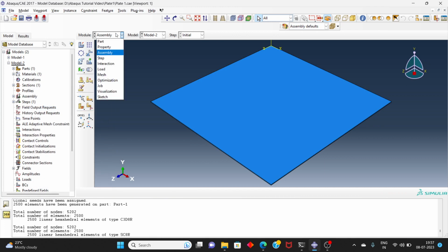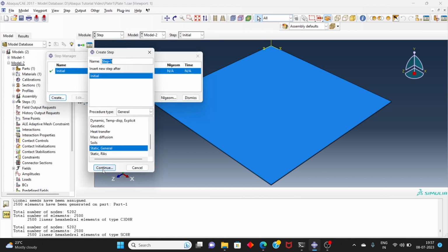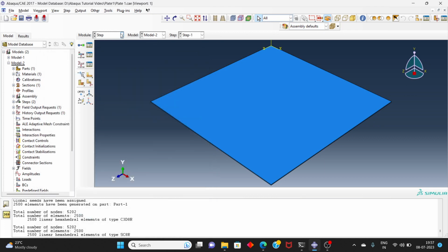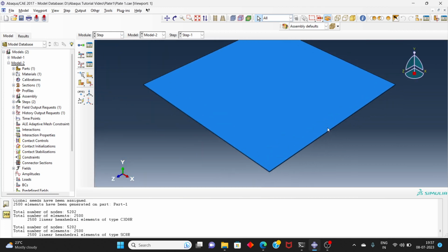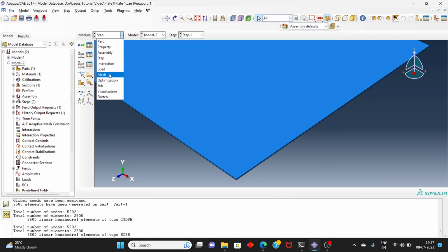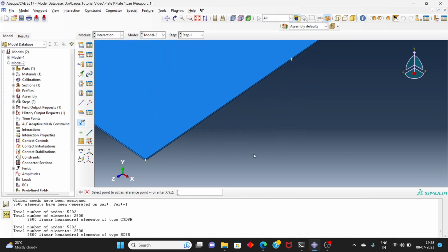Now most of the work is done. Now this is the repetitive task which we use in all other models. Static, nonlinear geometry done. And all right, so this is a 3D part. So how do we apply the loads now? We have to again make a reference point here, or else we can apply a pressure load on this particular end, but we'll keep the same method we have been using so far. No new creativity, let's not go for that.